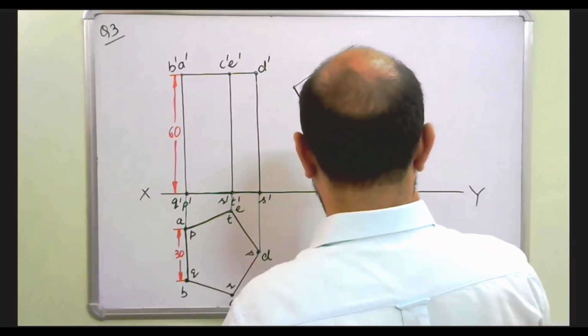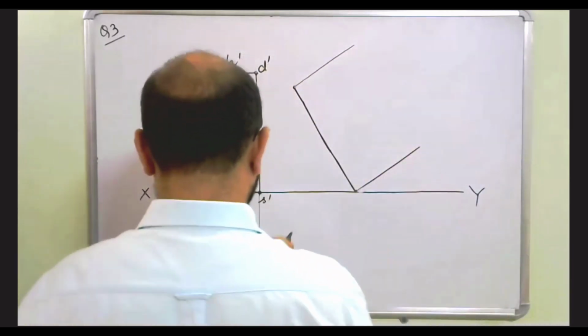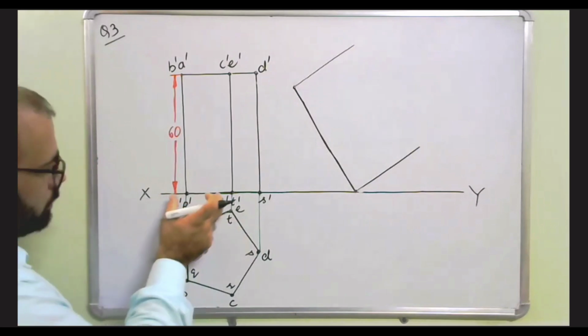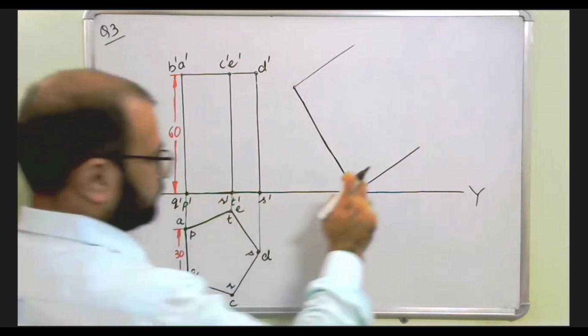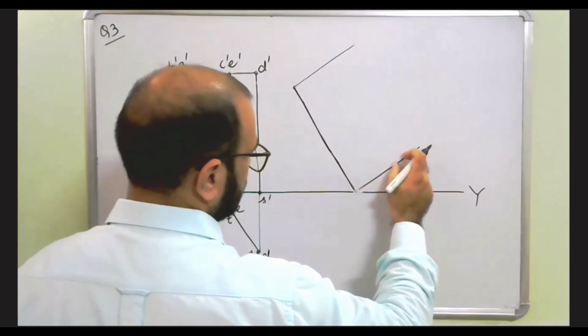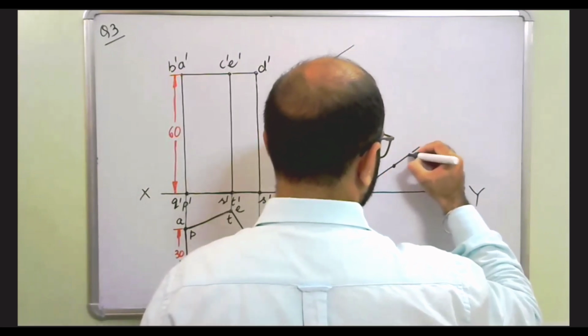Draw two perpendicular lines. So it should be equal to this, right? So one this, another this. So what you can do, you just mark an arc over here and mark an arc over here. This is the first point. This is the second point.